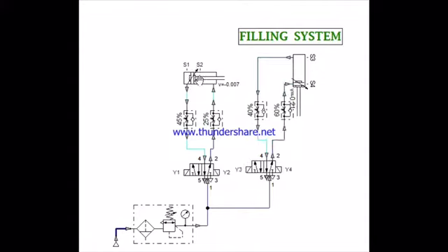After it actuated to S2, then the 5/2 valve solenoid at Y1 will be triggered. Then cylinder in S3 will actuate to S4. After that, it will transfer to the next process.